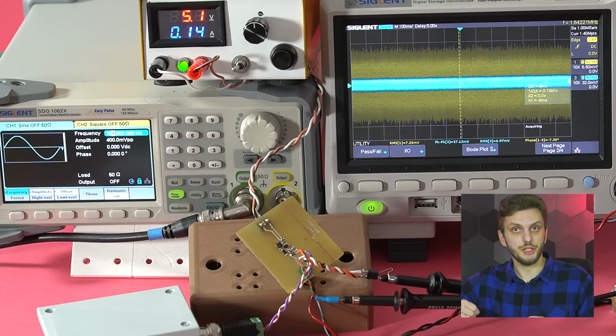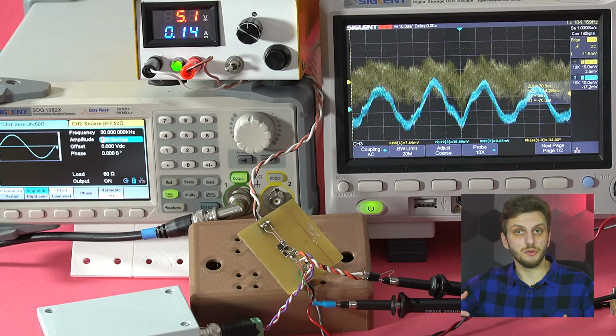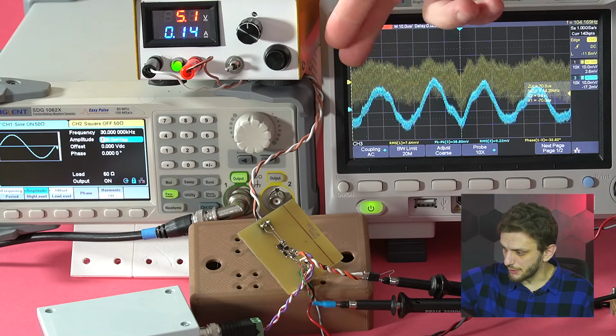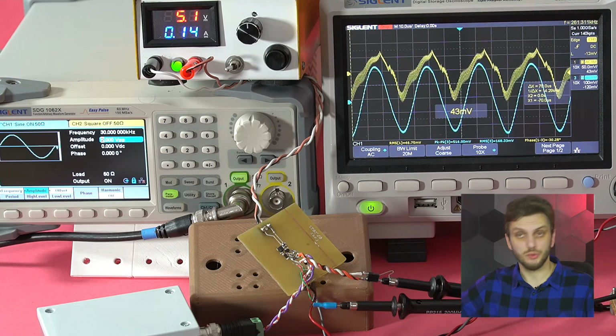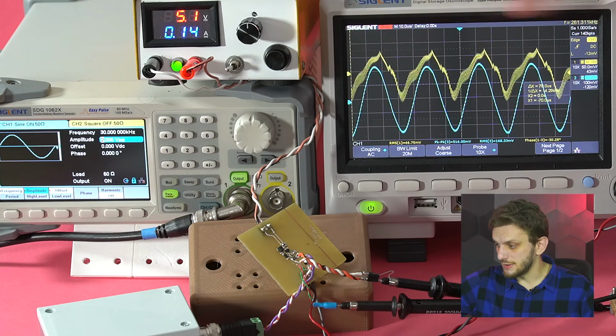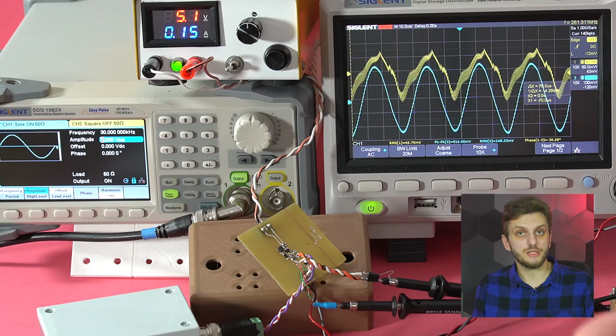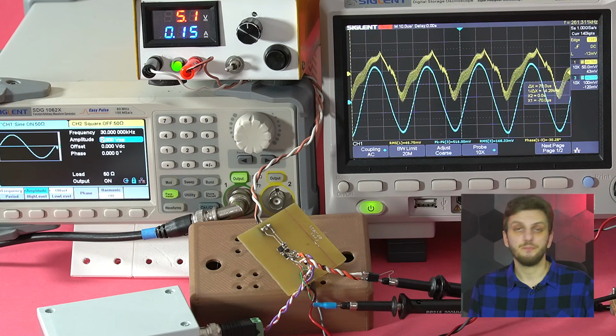Now, before proceeding to the actual measurement, it's important to check the behavior of the supply when the test signal gets injected. So if the test signal that is getting injected is too small, it will be too noisy and very difficult to measure, so you can barely see something in the yellow line. And on the other hand, if the signal is too large, then it will end up getting distorted. So what you're trying to look for is nice sine waves on both channels, so on both sides of the isolation transformer. If you don't have that and you have something like this, most likely you will end up getting some false results. So it's important to find a signal amplitude value for which the measurement can be done without distorting signals.